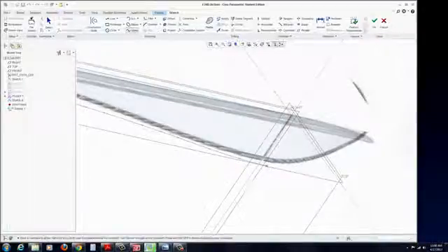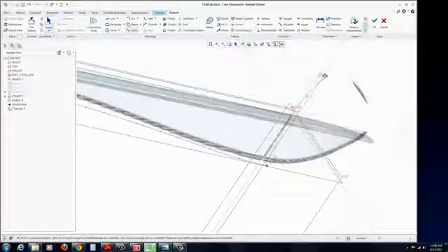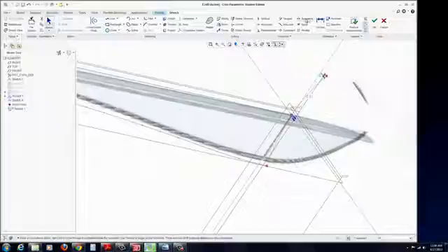Connect to this end here. Connect to that center. And then out here somewhere, kind of click and a middle click. So you have 3 points. Now take a center line and right at the center there, draw a center line. And that's so you could now add a symmetric relationship between the two sides.